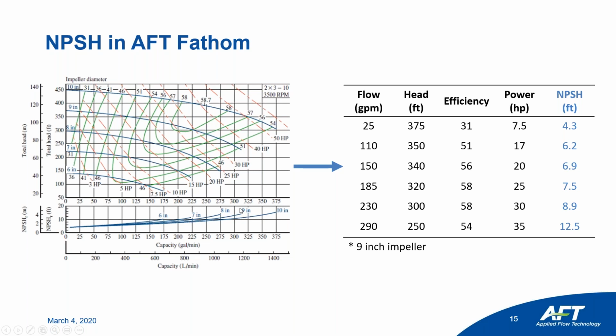And so remember with that preferred operating region and that allowable operating region, how we could go all the way down to 50% of BEP flow, but we could only go 15% above it. That's another contributing factor, in addition to that vibration effect, is now you're much more likely to see cavitation.